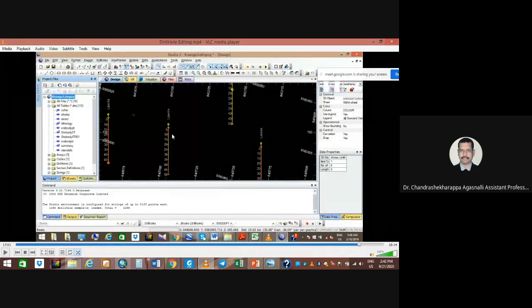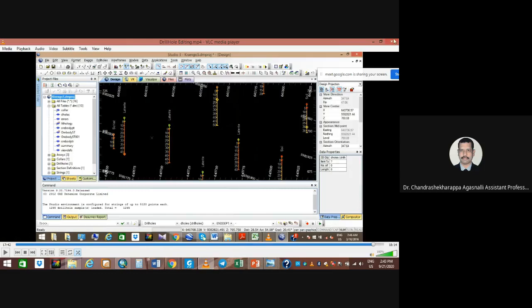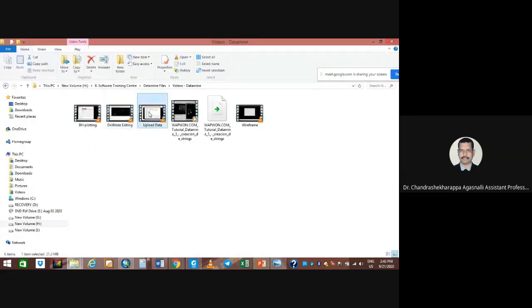Here you can see this. From 0 to 5 meters, one lithology in different formations. For all these boreholes, we are going to do the cross sections, and we are going to do the 3D modeling, which uses the triangulated irregular network. We call it a TIN, and also a DTM, digital terrain model. That is the best example.